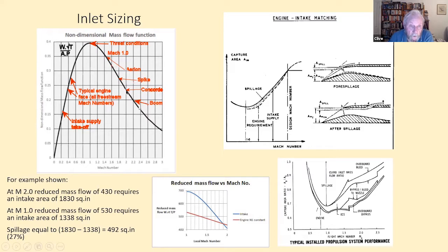For the record, Concorde sits there. Boom, which is going to fly at Mach 2.2, HOTOL will actually be worse. Spike 512 at 1.8 would be better. And the Aerion might actually get away with it because it's not all that different at Mach 1.4 to the Mach 1. So Aerion, the spillage could be quite sensible.